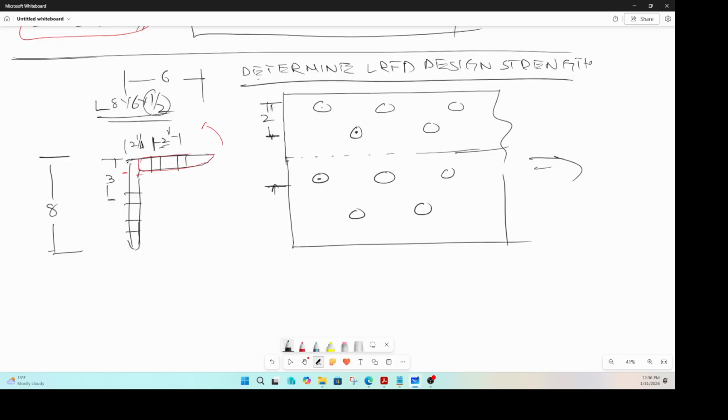That distance from here to the center line of this bolt hole is 3. From there to here is 2 plus 2.25, but you lose one thickness because of this cut and paste job, which is half an inch. So this comes down to 3 plus 2.25 minus half inch, which is 4 and 3/4.